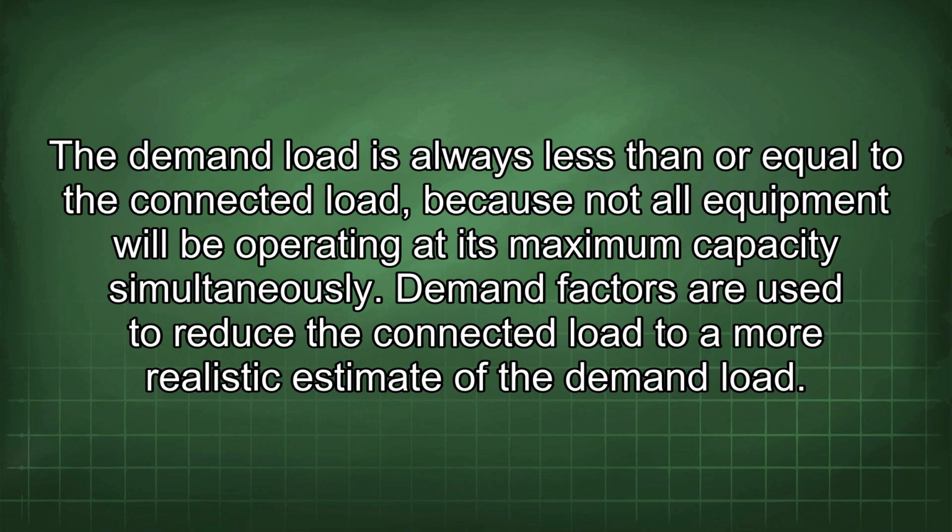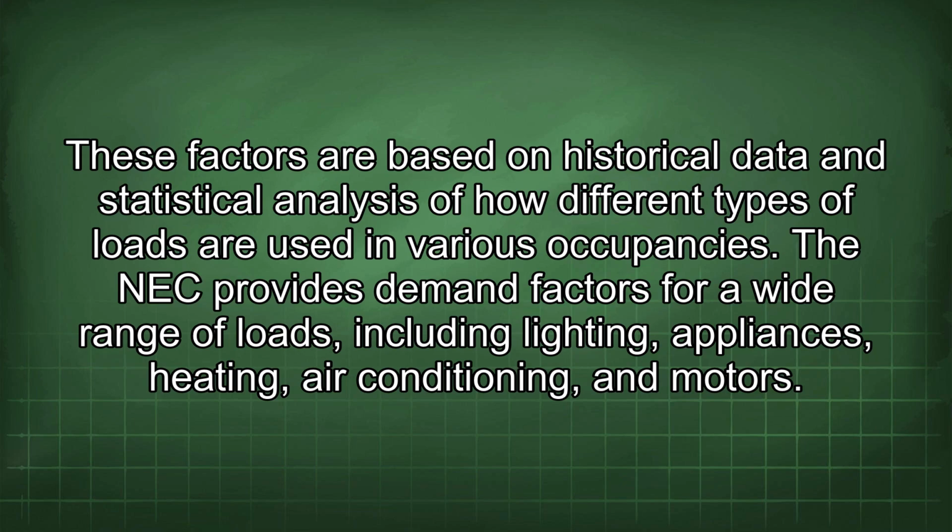Demand factors are used to reduce the connected load to a more realistic estimate of the demand load. These factors are based on historical data and statistical analysis of how different types of loads are used in various occupancies. The NEC provides demand factors for a wide range of loads, including lighting, appliances, heating, air conditioning, and motors.